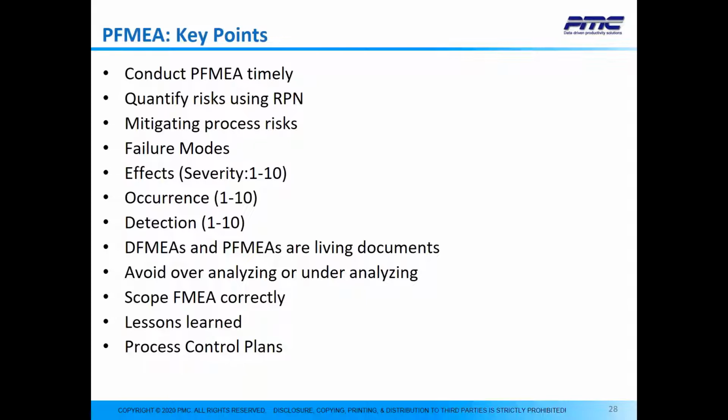The FMEAs and the PFMEAs will be performed ideally with members who are common to both teams to facilitate the concurrent design and build efforts. The reason we're stating this is that if you have 2 totally different teams focused on each of these risk assessments, the knowledge is not going to carry over from one risk assessment to the next. So the result is not going to be as good as you expect, and plus, I think it will take even longer to actually complete both assessments.